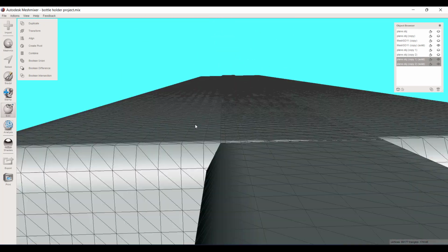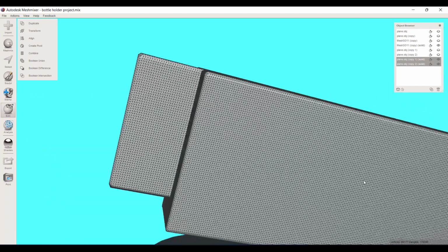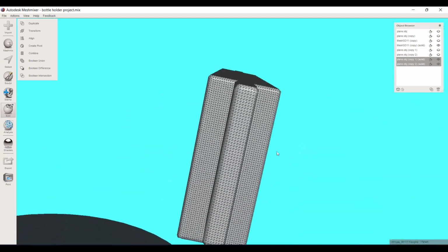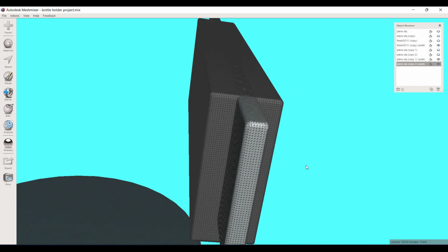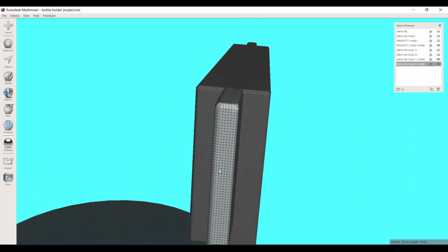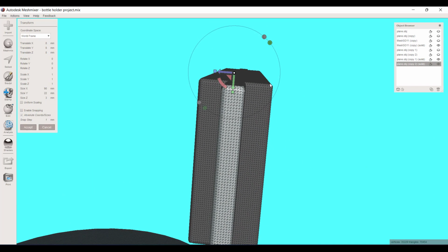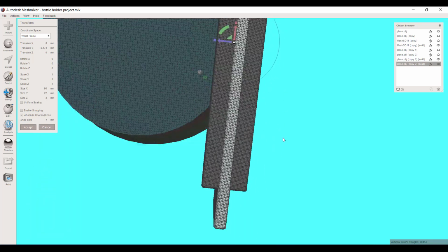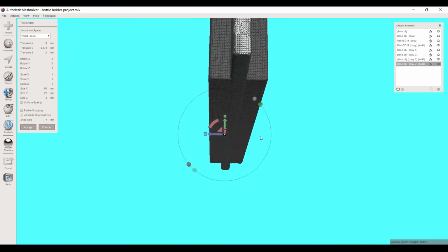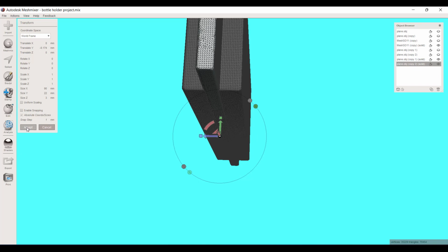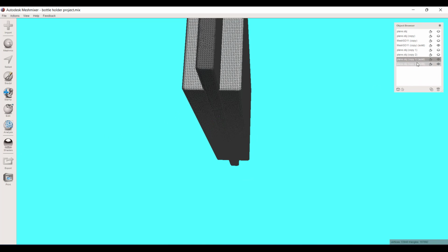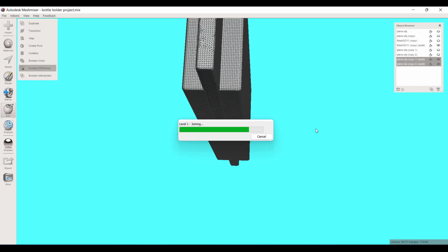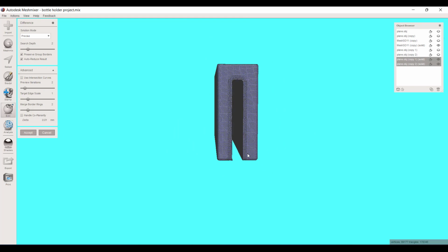So let's cancel that. I could fix this by, well, easiest thing, let's just transform this. Again, this is not a precision part. What if I just scoot this up? I mean, even like a tenth of a millimeter. Now that thing is cleanly shining through the bottom of it. And so now when I do that Boolean subtraction, I should have a really good result. There we go.